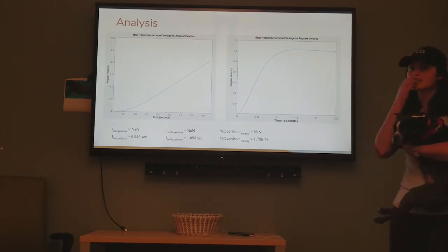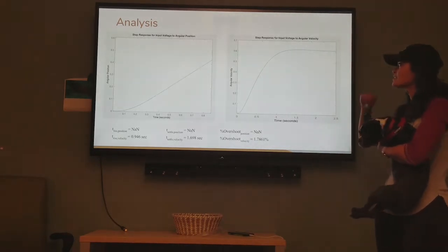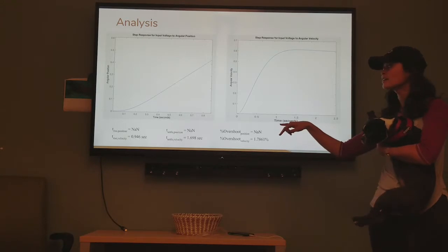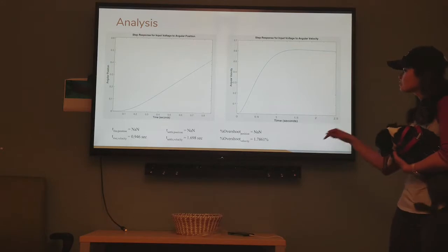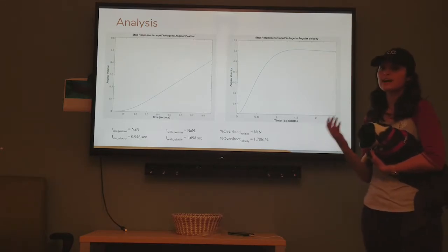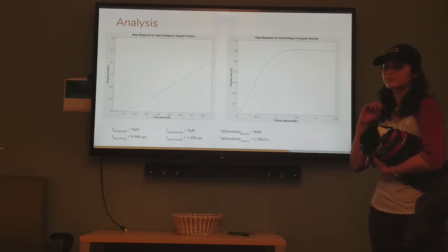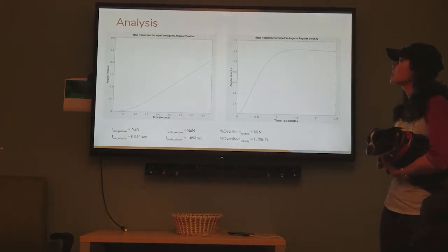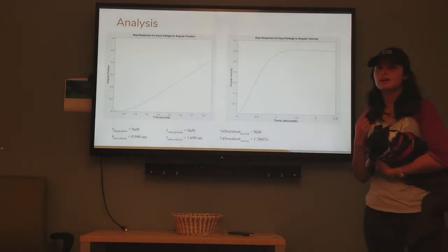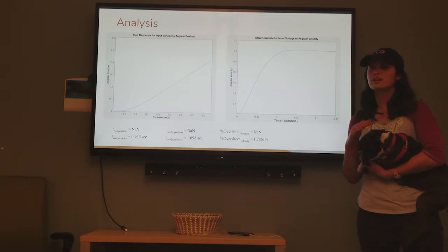Whereas our angular velocity is actually leveling off, and it has a settling time, which is approximately 1.7 seconds right now. And right now it has a little bit of overshoot, which wouldn't be ideal in our situation because it would lead to error in where the telesurgery robot was cutting into the patient. However, it does settle off, which is acceptable because we don't want the robot to continuously be speeding up through the process.